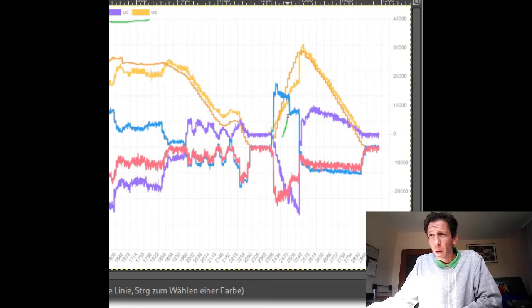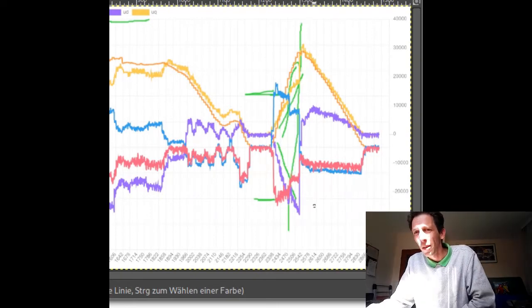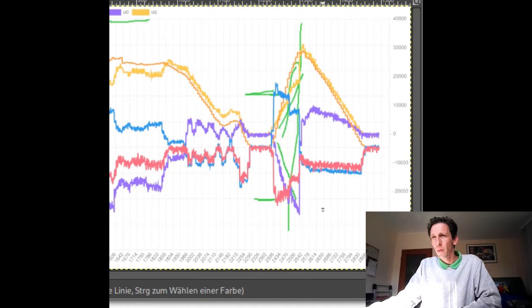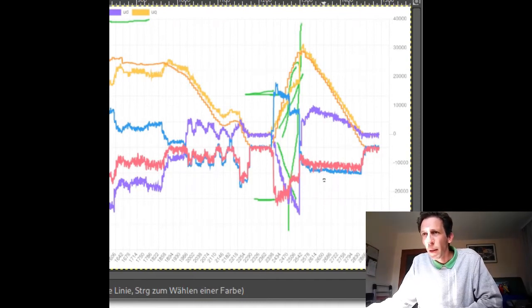So yeah, here we see another acceleration as denoted by the quick rise in frequency. And again we can see pretty much constant current values. And we can see the voltage values rise with frequency to maintain the current. Now, at this point, I seem to have stopped. Oh, very good at drawing straight lines. I seem to have stopped accelerating and went straight into regen. And now we can see something interesting.